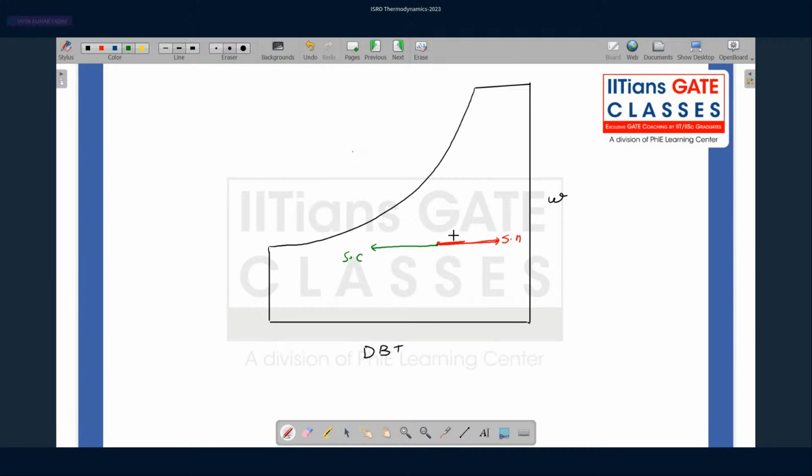Yes, because in this horizontal line there is no change in humidity, so it is sensible heating or sensible cooling. Now if you go up, it is simple humidification. If you go down, this is simple dehumidification. So what are the two processes that are happening in your case?